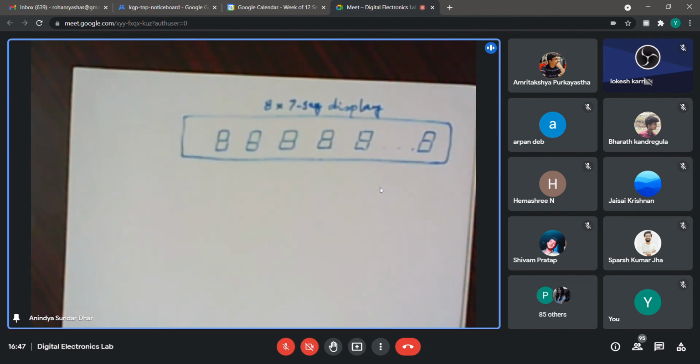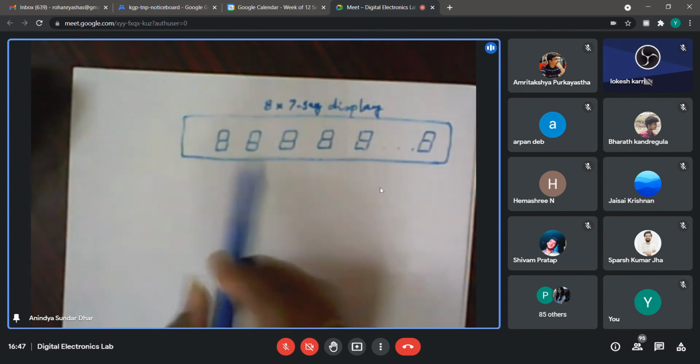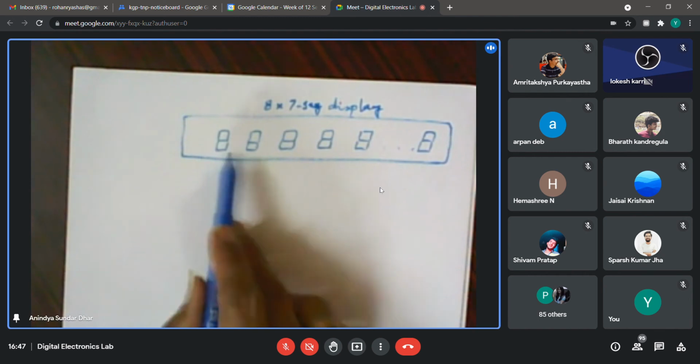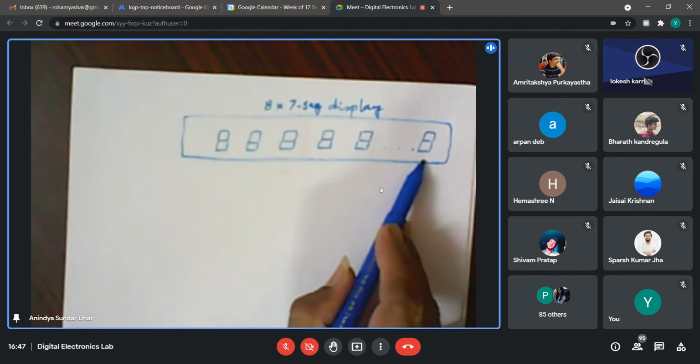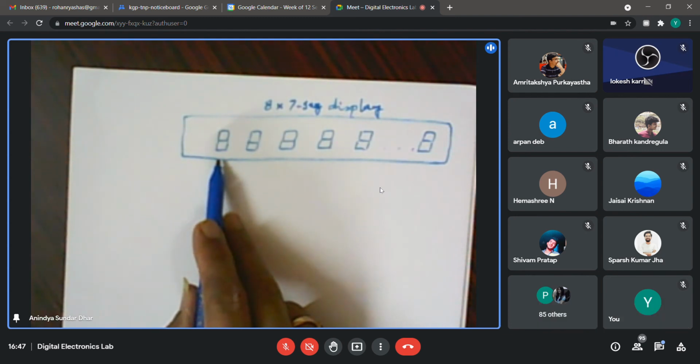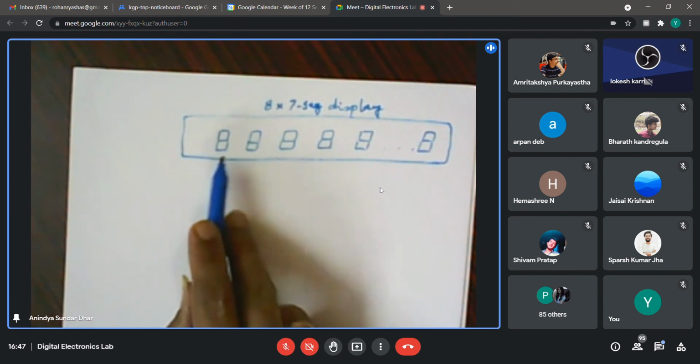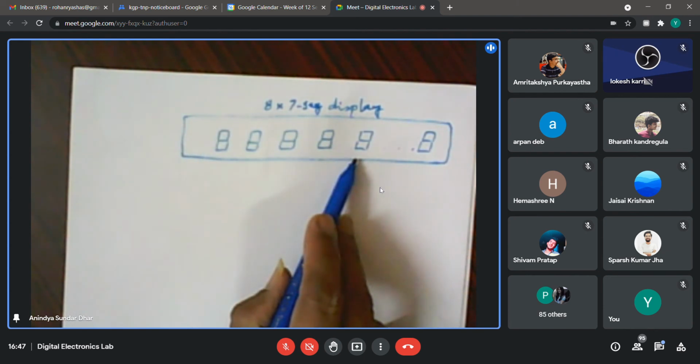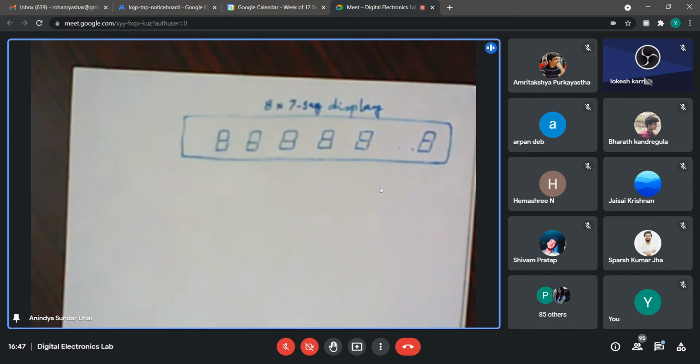Okay, so is there any possibility of reducing that? First thing, maybe we can reduce it to some extent. If we put the 7447 on the board itself, then maybe for each of them, rather than 7, I can send 4 lines. So most probably Ajay is saying why not 32. You are thinking that if I put the 7447 here, it becomes 4 lines per character per board, 32 plus power supply lines. So maybe 32 plus 2, 34 lines I need to send.